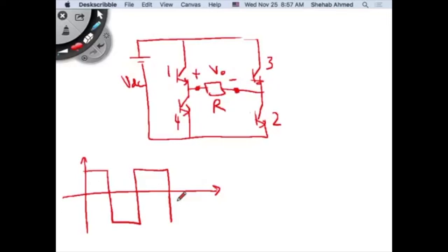And you cannot use a regular boost converter because we saw the limit on boosting ratio is what? 4 times, for example. So from 12, you cannot boost to 180 volts. No way. So what's the solution? The solution is always a transformer. AC, but transformers do not allow you to translate DC voltages. They only allow you to translate AC voltages, right?